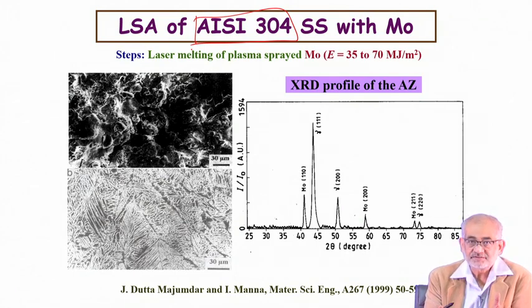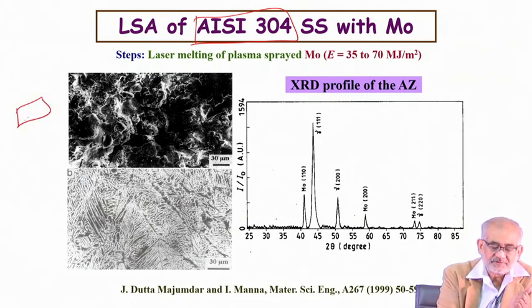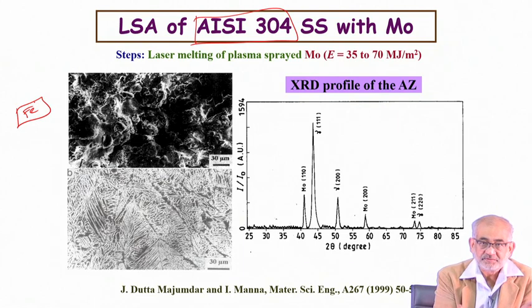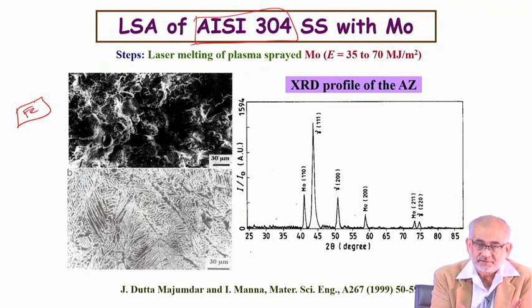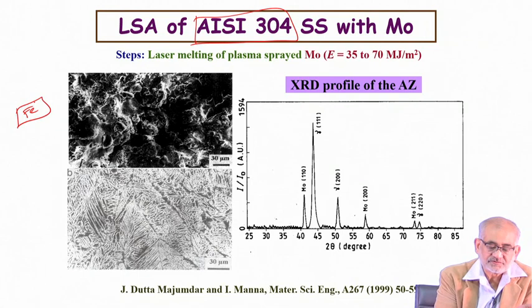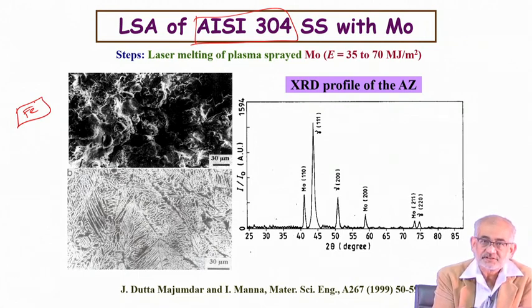In order to understand this, if this is iron and you expose it to any corrosive atmosphere, it will immediately form iron oxide and iron hydroxide or certain carbonates and so on, and they fall off and then expose a fresh layer and oxidation continues, and that's how it gets corroded.